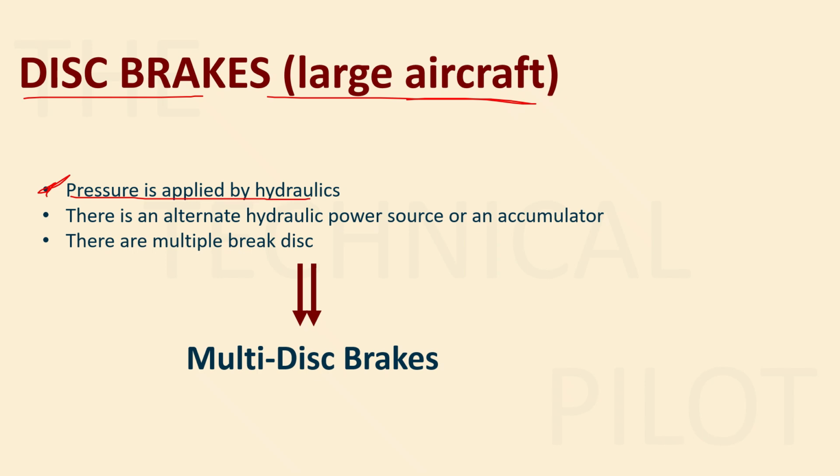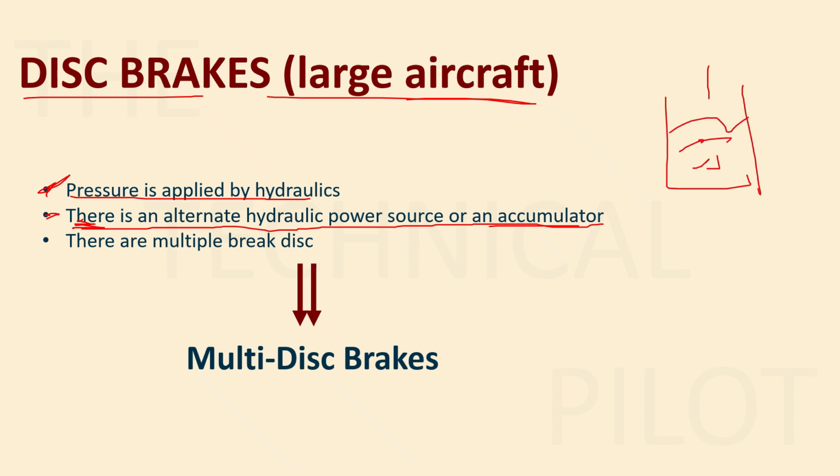And whenever we are using hydraulics, what do we need? A backup system, right? In case of a hydraulic failure, there is an alternate hydraulic power source or an accumulator. An accumulator stores your hydraulic fluid under pressure. This we studied in hydraulics. If you haven't watched that video, go ahead and watch it. So the third point is that there are multiple brake discs. This we'll see in detail.